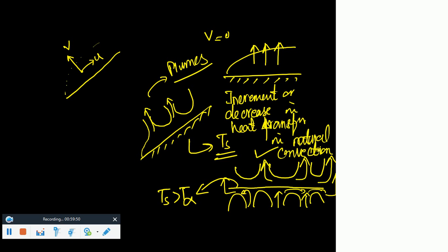You should be able to answer that, isn't it? And that answer would not be coming through something which you have already learned in case of forced convection. You should keep natural convection in your mind. If you keep the flat plate over there, would it try to increase the heat transfer or not? If you keep the plate like this, what would it do with the electronic equipment? Because if natural convection mechanisms are not properly designed, it would do what? It would heat the equipment and suddenly it would simply blow up.